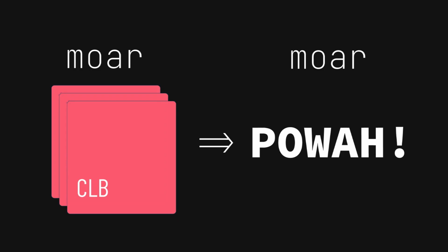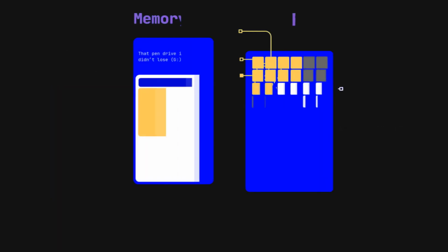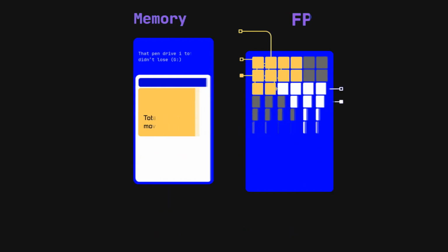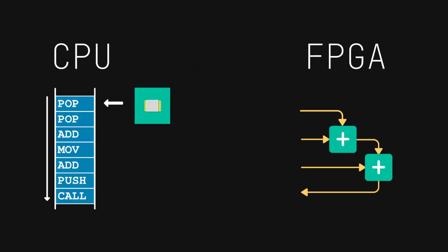Their limitation is usually their size. Size here means the amount of CLBs we have. Mine, for instance, has 25K CLBs. In a funky way, they're analogous to memory storage. The same way you allocate memory to store data, an FPGA allows you to allocate some of it to store digital circuits. Comparing FPGAs to processors, we see that both can solve many problems, but they do so using essentially